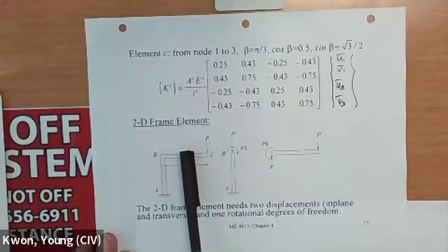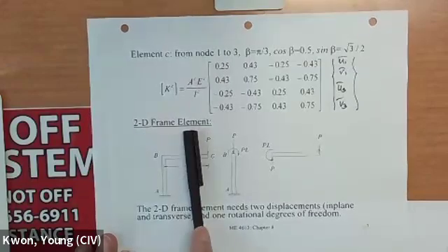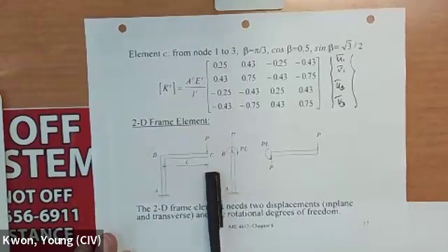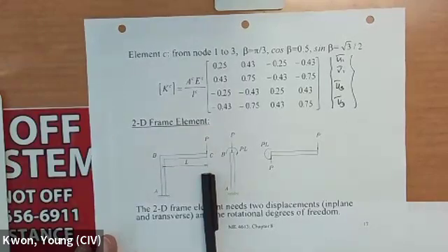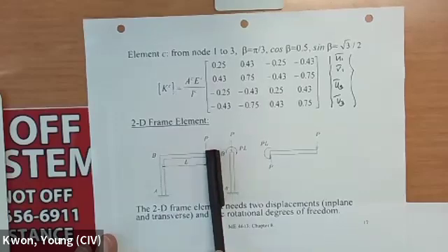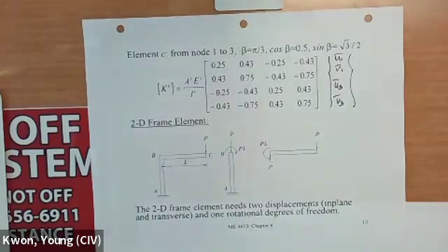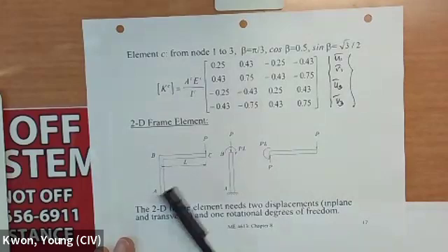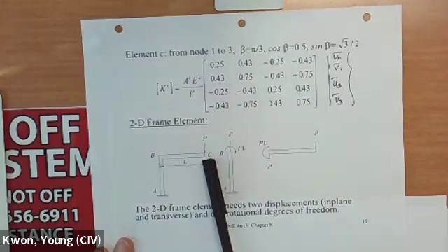So today we want to continue to talk about the 2D frame, not the truss, but the frame. So what is the difference of a frame? To illustrate the example of a frame, this is an inverted L-shaped frame, like a bracket, fixed at A, and a force is applied at the tip at C. To illustrate why this is a frame, you just draw the free body diagram of member AB and member BC.